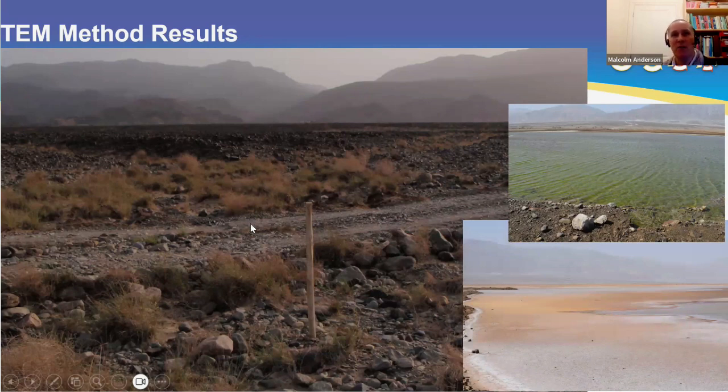And is that water fresh or is it salty? So we would want to use ERT, the resistivity method, but the thing about electrical pins is that sands and gravels have a very high resistivity, and it's often very difficult to get a good electrical contact using the resistivity method. So this is where the TEM method comes into its own, because it doesn't need a contact and you can just walk over the sands and gravels.